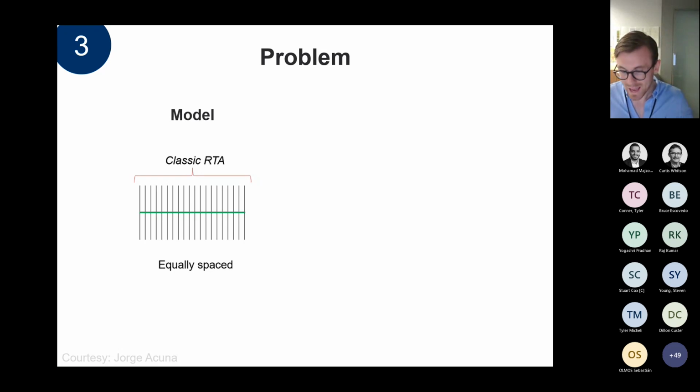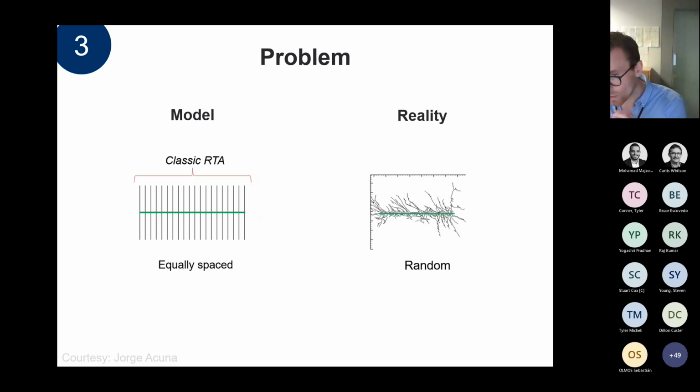It means that any boundary effects we actually observe in real field data, we have to then simplify into one boundary. And we also have to simplify and say we're seeing all of those boundary effects at the same point in time. The problem with that is that in reality, we might be dealing with something much more complex, where we see boundaries at different points in time. So probably the dominant flow regime in many of these wells is not infinite acting or maybe boundary dominated. It can actually be transitional.